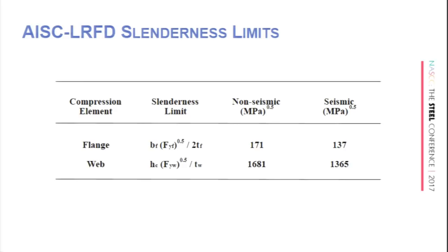Okay, I have this issue right now with the design authority that I am working, actually, I review papers from the design authority, but I represent the owner. I'm working at Vogtle Nuclear Power Plant, which is under construction right now. And the problem was they did their slenderness calculations, and we're using old codes. We're using the nuclear code N690 1994, which is really the sister code to the infamous ASD Green Book, or the 9th edition. Okay? And so in the 9th edition, it's 65 over the square root of Fy. In your current edition, whether it's 2005, 2010, 2016, it's 0.38 times the square root of E over Fy, because we put the E back in.